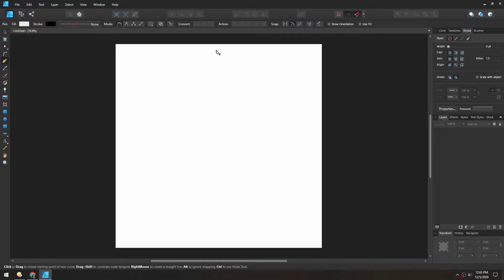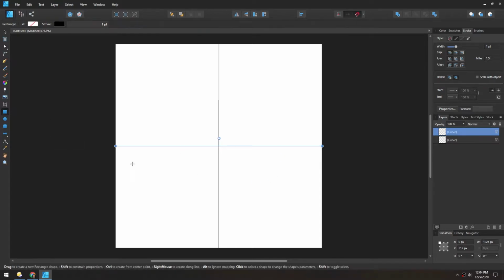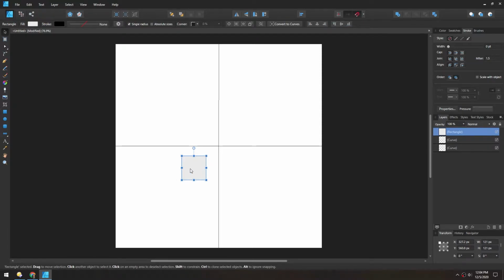So I'll draw the center lines. And with snapping enabled, it's really easy to find where the center is. It just kind of snaps right to it. So now we have 4 quadrants. We can just make a simple cube in one of them and hit V to move it around. And I'll be mirroring this over this axis, so I'll just drag it and snap it there.